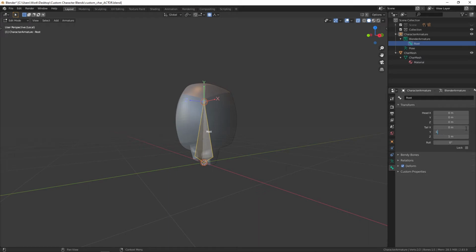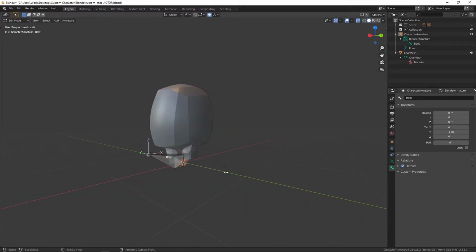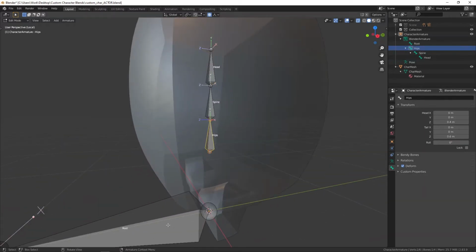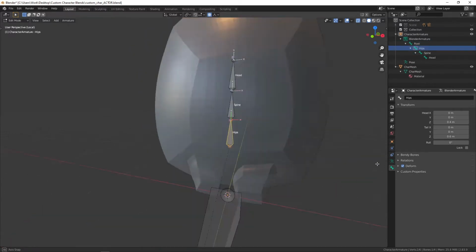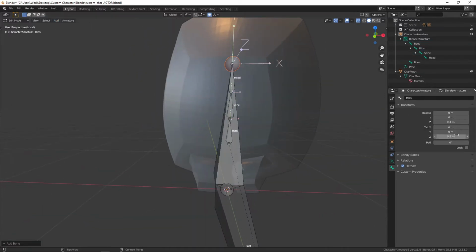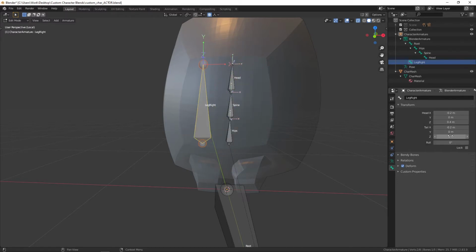For the root bone, I'm going to have the tail of it set in Blender in the negative Y direction. But the local orientation will be just like Lumberyard, Y positive, Z up. I'll add a second bone for the hips, and then selecting the tail of the hips, I'll extrude two more. The extruded bones were parented automatically, and they were parented right, but the hips aren't parented to root yet. So I'll select the hips first, and then control click on root, and Control P to parent and keep the offset.